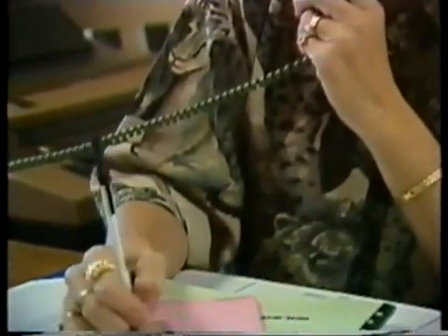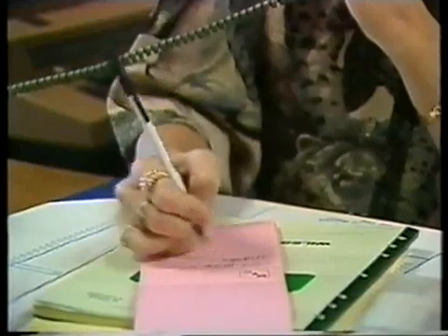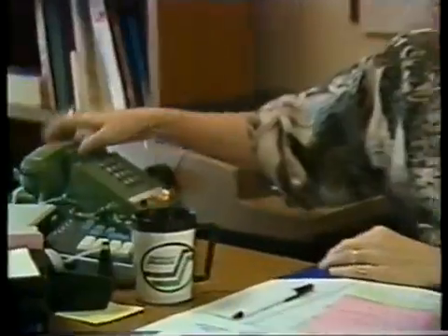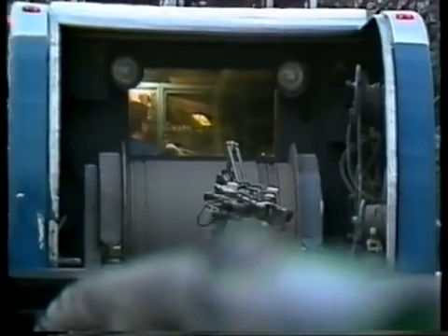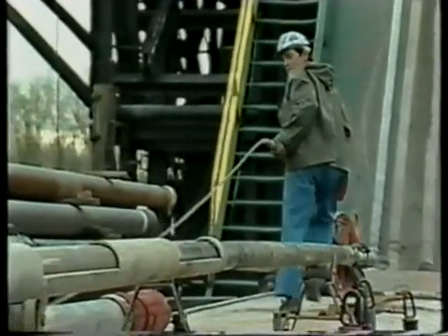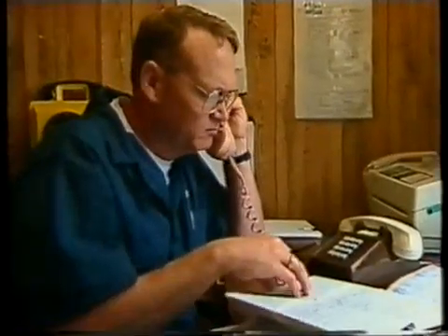At this time, the oil company representative and the service company will often agree upon the amount of lead time required to notify the service company prior to logging. In remote and offshore areas, the logging crew may already be on site, depending on the type of service contract negotiated with the oil company representative. The objective of the notification is to provide adequate mobilization and setup time for the logging crew, and to minimize idle time either for the service company or the rig crew. At the time of notification, the oil company representative should again review the tools that are scheduled for the logging survey and update any well site conditions that may affect the survey.